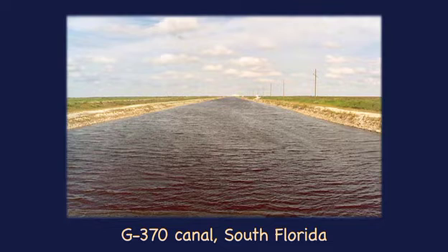Erodible channels are unlined earthen channels, which may be subject to erosion by the force of the flow. The design of erodible channels is substantially more complex than that of non-erodible channels. Particle entrainment is a function of bottom shear, which is proportional to the velocity. Excessive bottom shear and velocity can cause erosion.